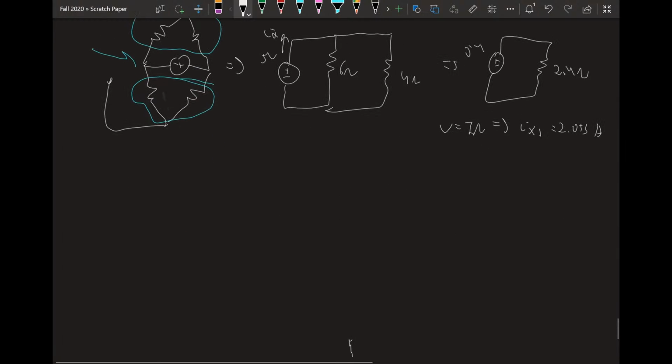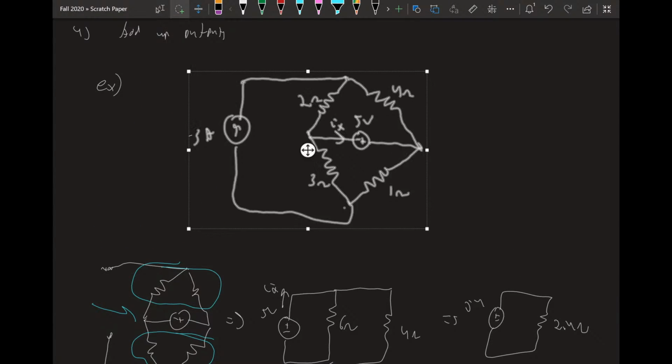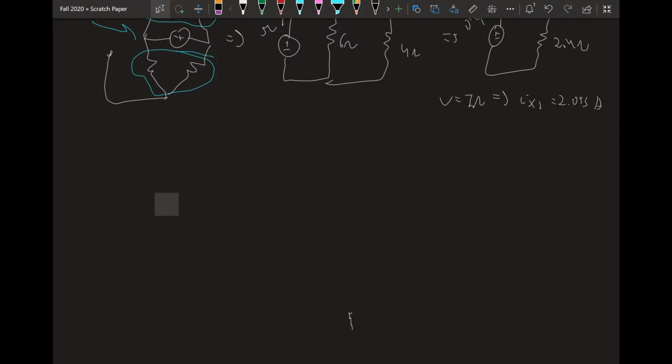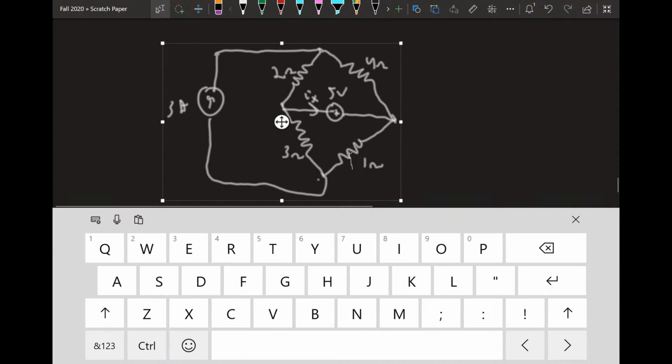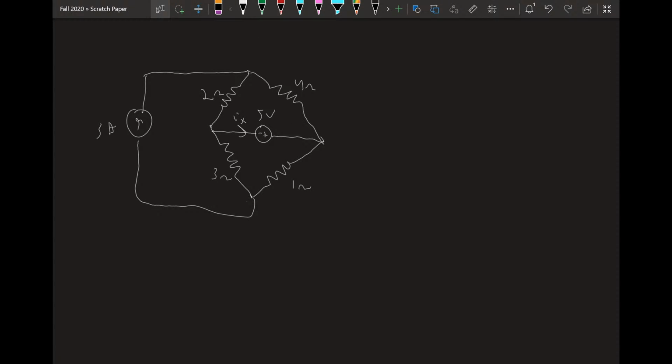Let's repeat. This time, deactivating the voltage source. Well, when we deactivate the voltage source, we get, let's see here. I don't want to redraw it. Let me use the power of technology and just copy paste it. Ah, look at that. And we're good. Okay. So let's deactivate this voltage source. To deactivate the voltage source, we want to get rid of that 5-volt thing in the middle, and that's going to be replaced with just a wire, right?